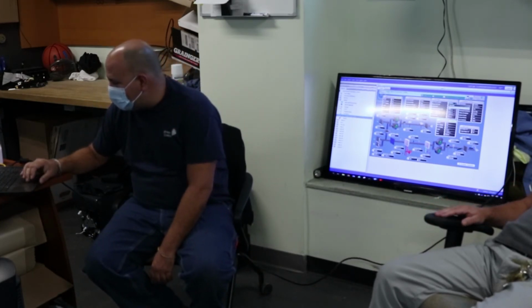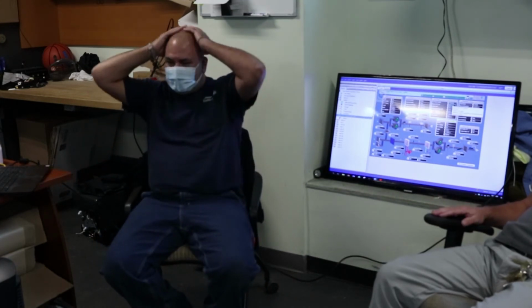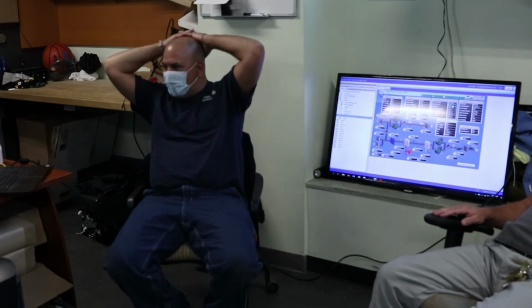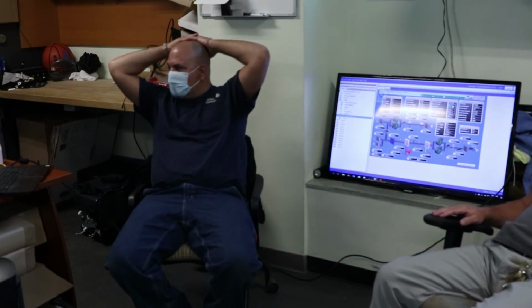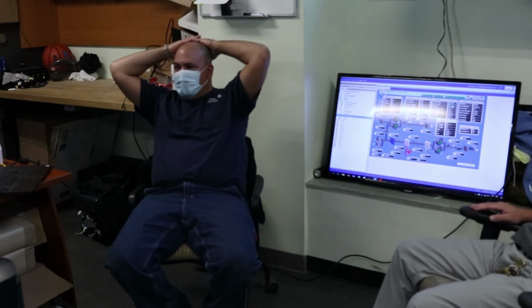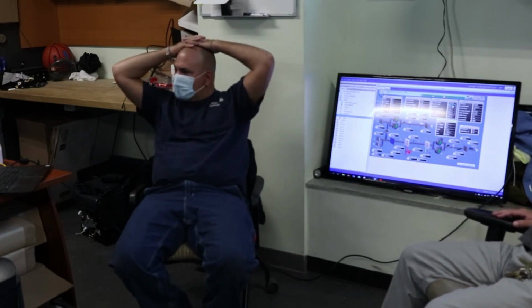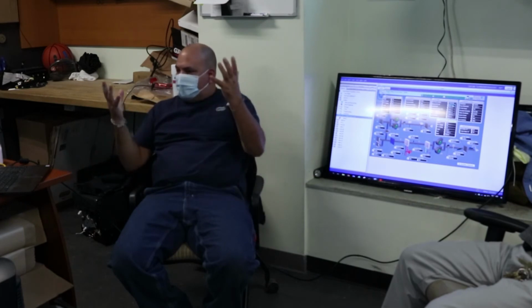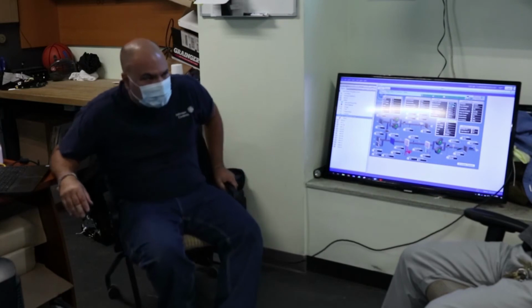I'm not a huge fan of the automatic reset based on the VAVs. I like VAV systems to be at 55 degrees and leave it on. You think it's better to put it on manual? Yeah, the reheats here are really small, but they do a pretty good job. The VAV box reheats, I heard they're like red boxes or something. Really small, basically the size of the VAV box, 10 by 12.